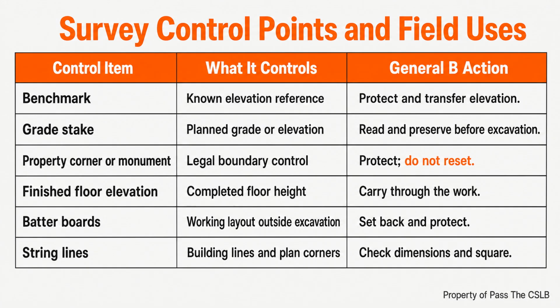Ask what monuments are on or near the work. Ask which marks are temporary and which carry legal significance. Ask what will be destroyed by excavation. Then place physical protection around important control and tell the equipment operators what cannot be touched.